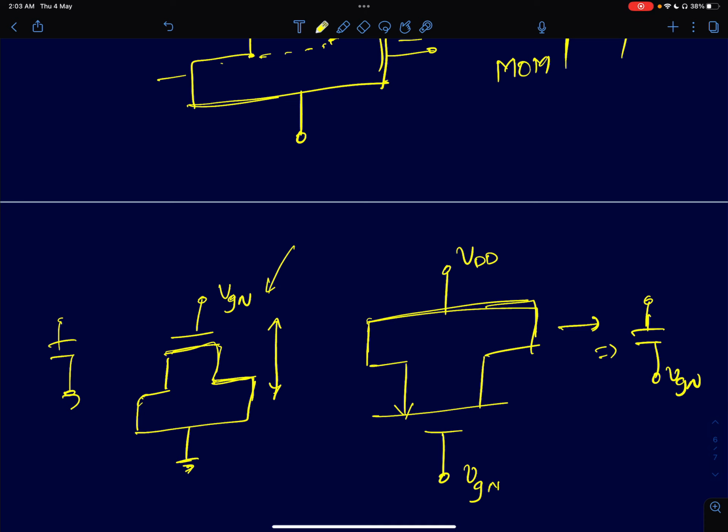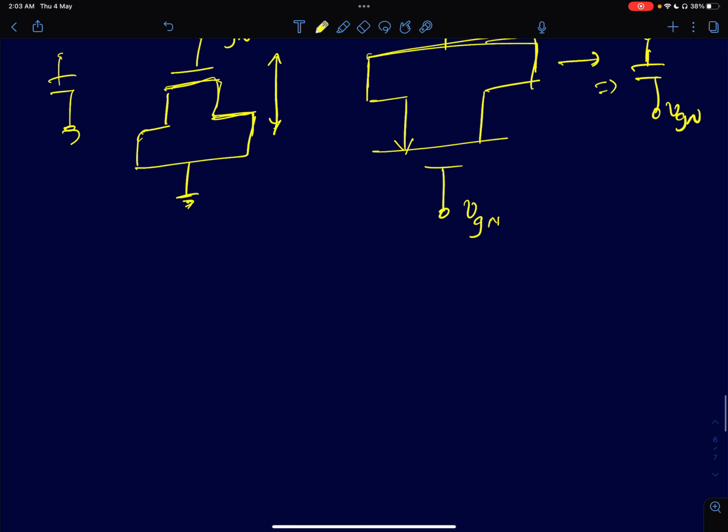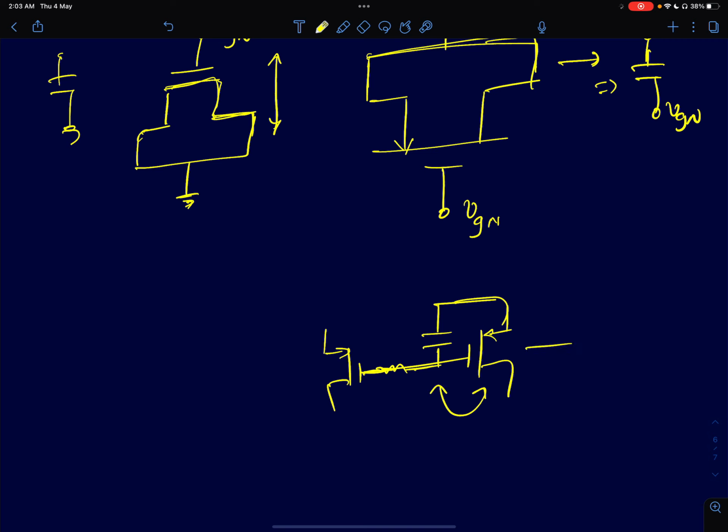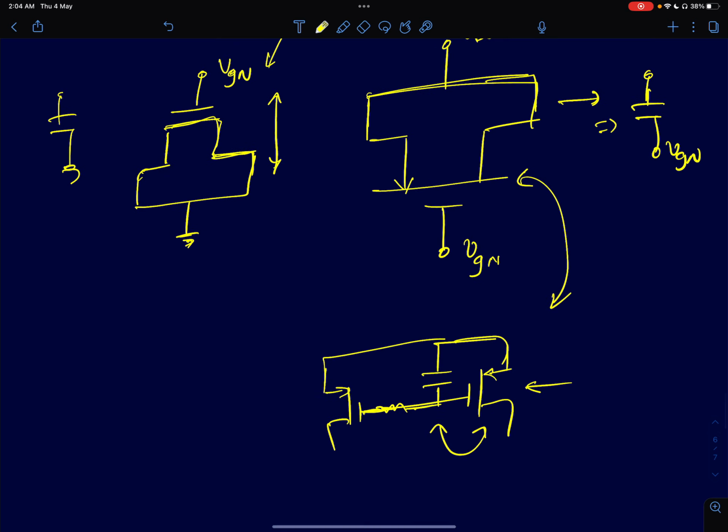Now, in current mirrors, for example, a PMOS current mirror, you already have this current mirror structure. What we normally do is that the resistor is realized using a linear region MOSFET, and the supply referred capacitor also happens to be a similar device as the current mirroring device. Okay, it's typically a PMOS device which is connected in this configuration, which is much easier. You already get it, and you just add this capacitor this way. Okay, and I have already discussed this previously as well.